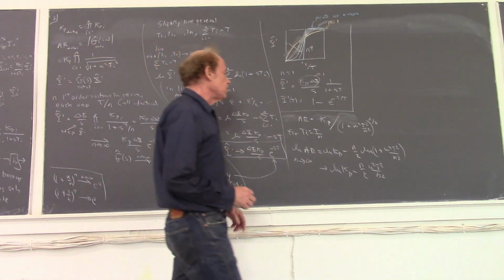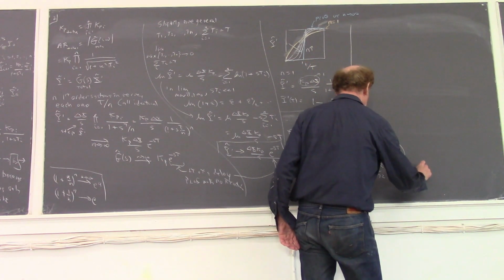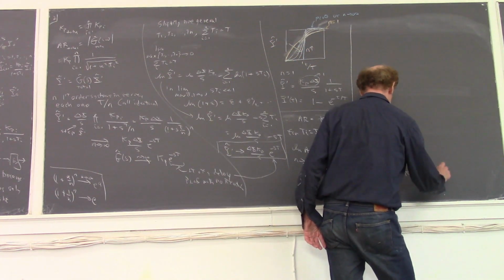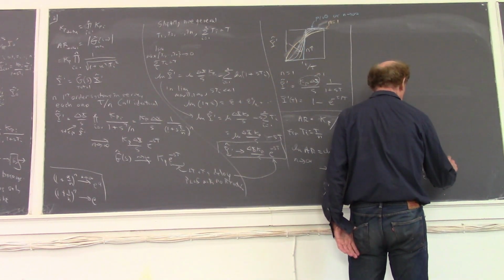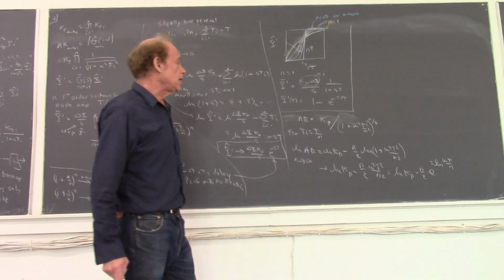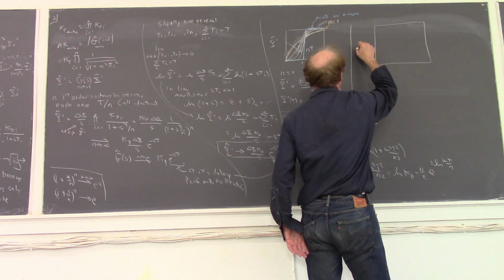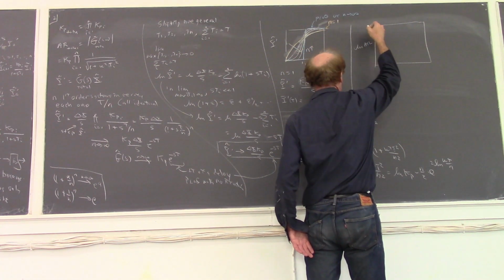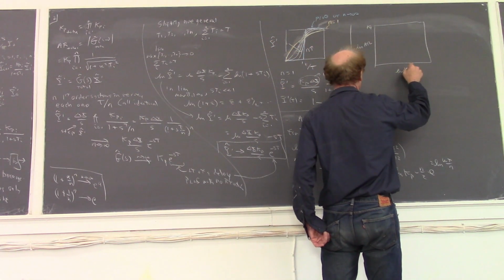So what does that look like? Well, notice that I can write this as log of Kp minus n over 2 times e to the log of omega squared T squared over n squared, or 2 log omega T over n. And why do I write that? I write that because now I can plot the log of the amplitude ratio, and this is Kp, versus log omega T over n.